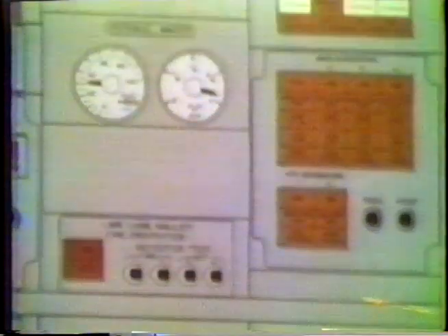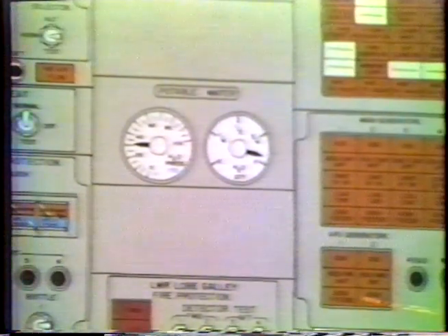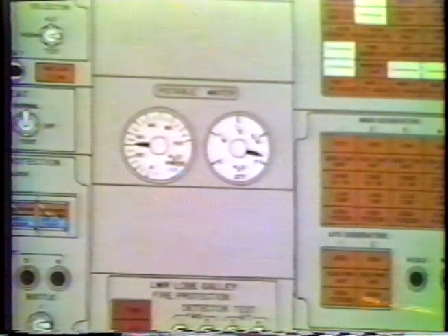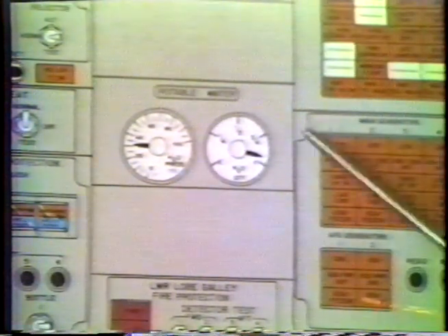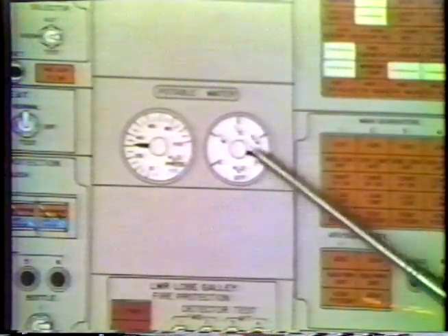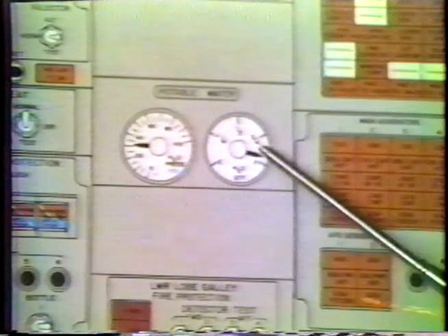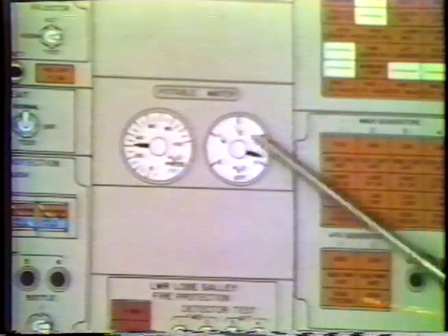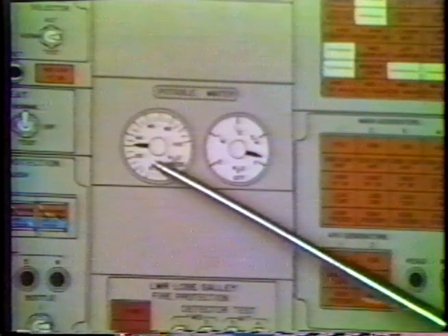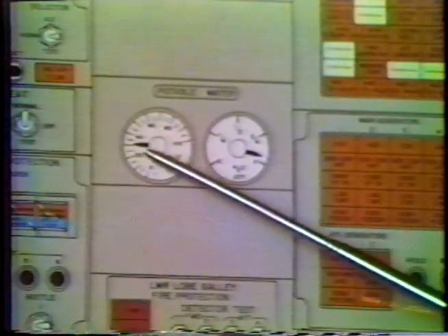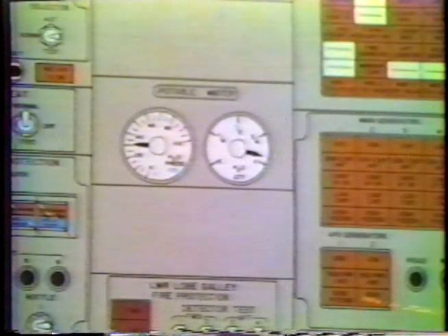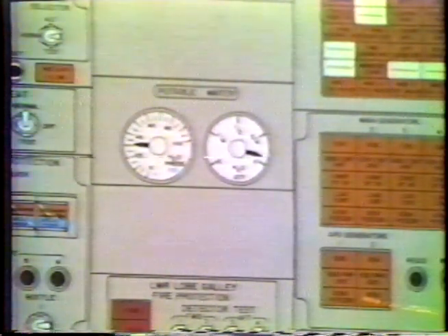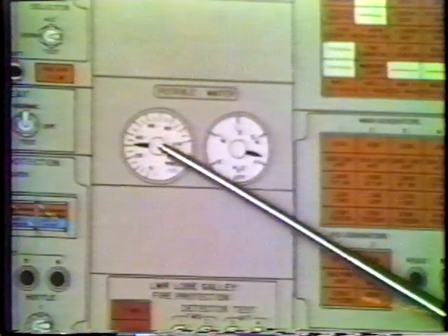Here we have a potable water system, indicators, and a gauge to tell you how much. Some aircraft have 3 tanks, some have 2 tanks. The amount is averaged by the tank. In other words, this is not one particular tank, it's averaged between all of them. And the hydraulic pressure, or air pressure that's available to hydraulically push the water to the various faucets and coffee makers and so on, is displayed by this gauge.